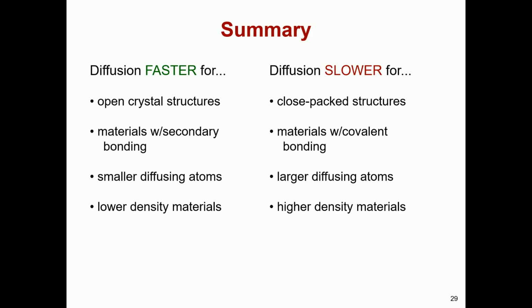However, remember that not all material combinations follow this diffusion physics. When incompatible materials are joined, they may not intermix even with heating. In these cases, different physical models and mathematical descriptions are needed. The diffusion principles discussed today apply when materials are compatible, where interdiffusion, self-diffusion and interstitial diffusion can occur readily between similar elements.